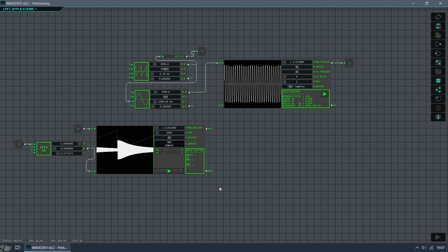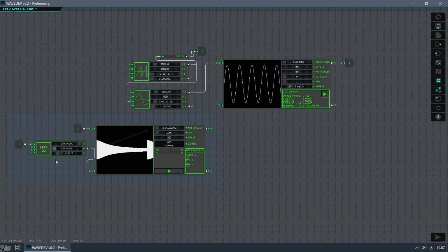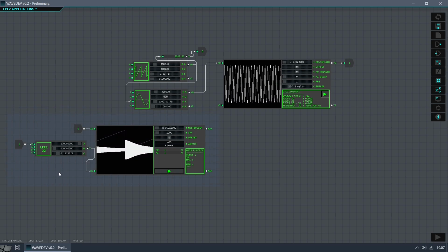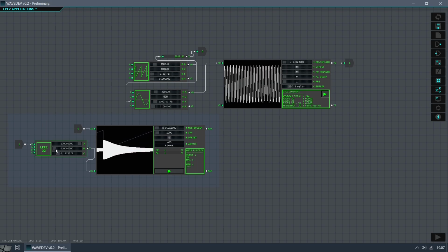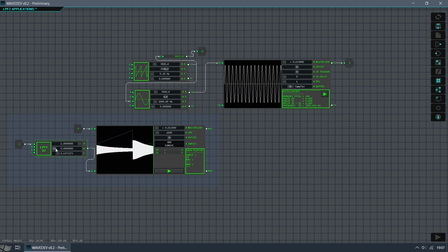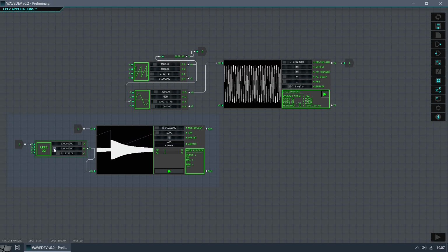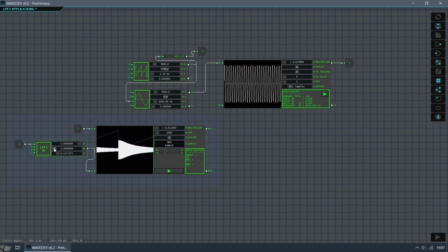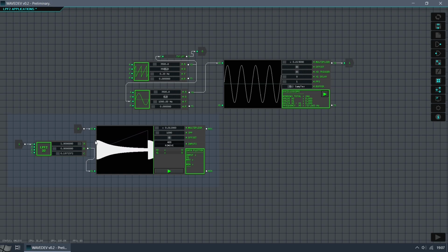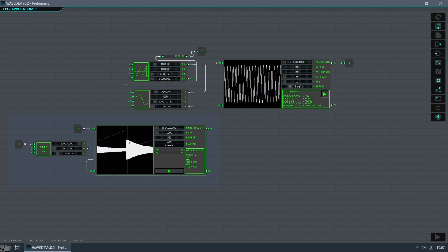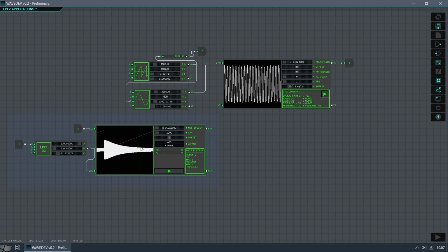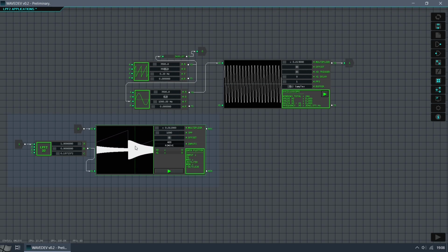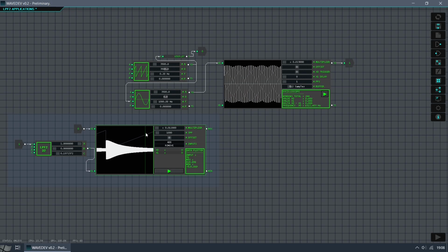So first we have the most basic operation of our filter. The first-order low-pass filter, which is achieved simply by omitting the resonance. This filter behaves pretty much like a passive resistor-capacitor filter. The white shape is the sine wave amplitude variation after filtering. It is seen how it attenuates as the frequency increases, represented by the gray line.